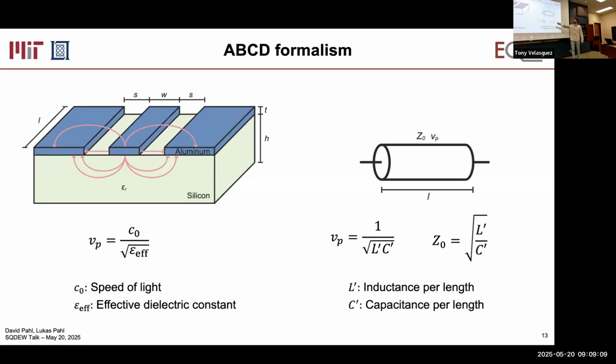And what this causes is that the fields sort of distribute in a coplanar fashion. They go to the sides. And then specifically those transmission lines also have a length and extent, right? And the physics that happens in these geometric elements can be abstracted with this model that I've been showing a lot, the transmission line, right? And it models traveling electric fields and waves. And we'll see later how it can efficiently capture everything that's going on in this layout.